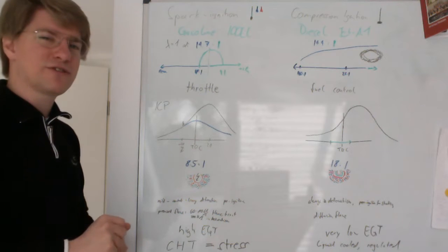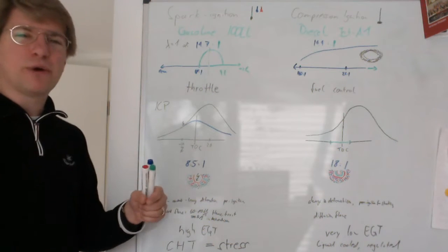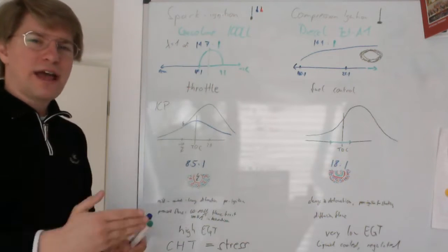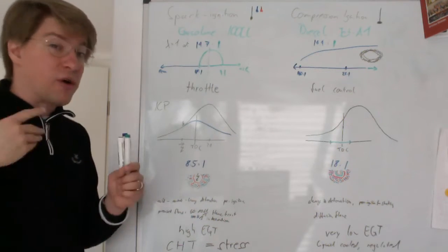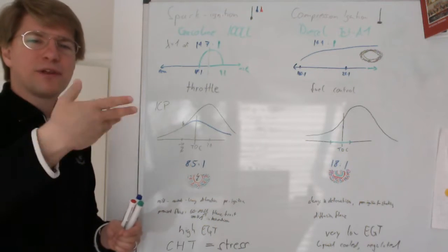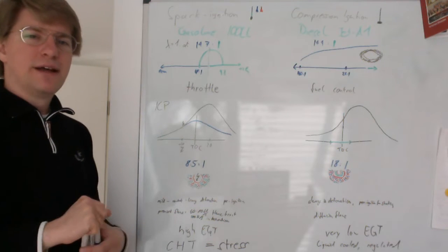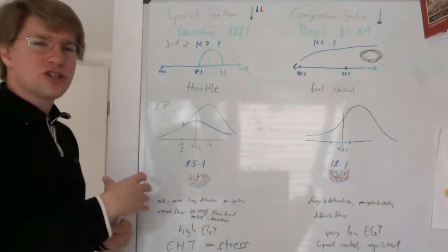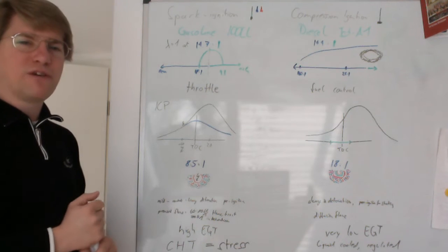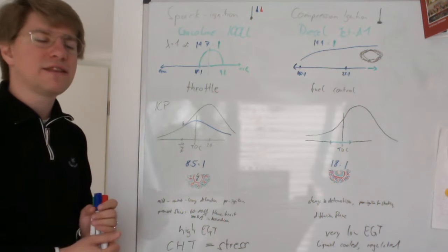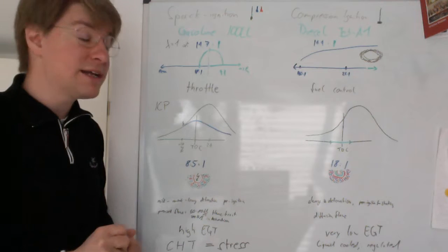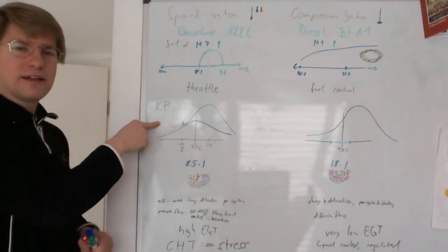We run at full volumetric efficiency, and because we're not anywhere near full power, we can run the engine at close to the ideal mixture, or even lean of the ideal mixture with very high EGTs without running into CHT limits. If you tried to run the engine at the optimal mixture at sea level with 30 inches of manifold pressure, most engines could not take this very long, because it drives up the cylinder head temperatures. And why does it do that? Let's look at the combustion process.